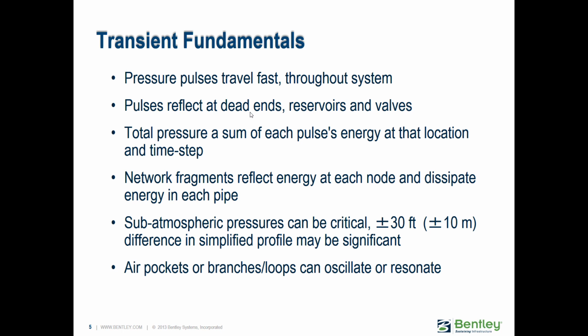So you really need to be careful about what elevations you include and make sure that those elevations are accurate. Those elevations should be the pipeline elevation, because that's the point we're measuring the pressure from, and it's significant when we're talking about at what point vapor forms. So we need to be consistent with that.